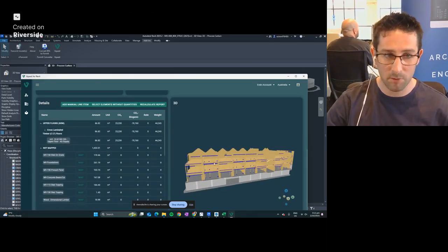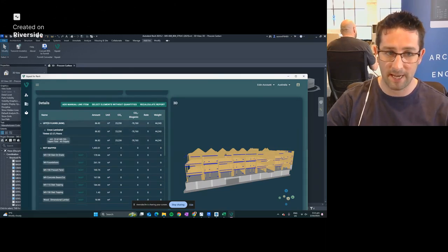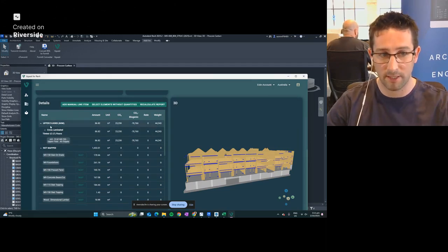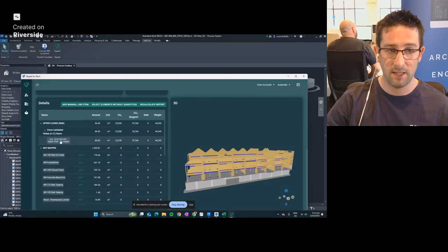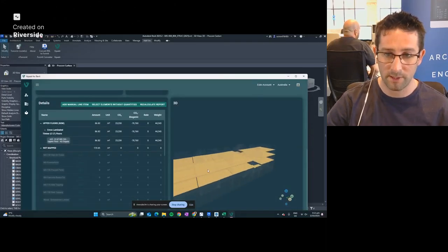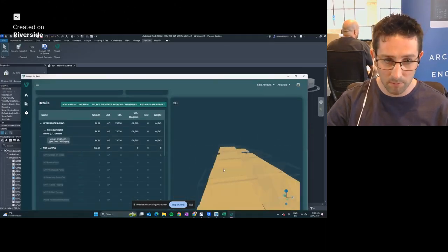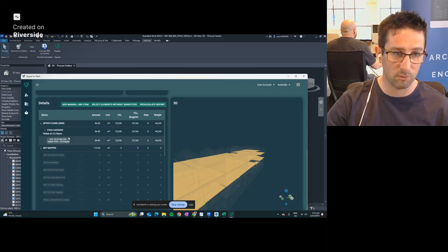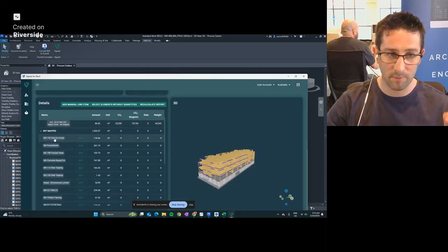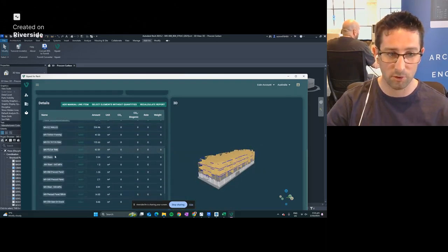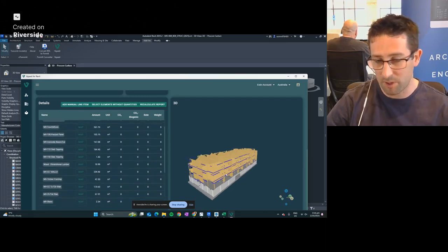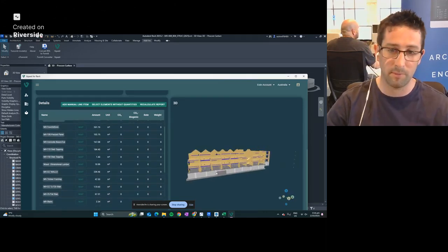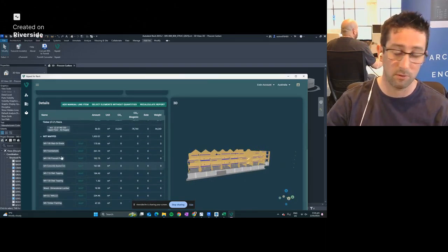That material that I mapped, which was the floor system, has actually been categorized. It's now under an elemental category of upper floors. And when we click here, not only do we see where the material is in the model, we can actually see the total quantity, the total upfront embodied carbon emissions, the stored carbon, the weight, and the cost of that material as well. So it would take about 5-10 minutes to work down through this list with these materials, but you can go as detailed as you want or as simplistic as you want with the level of detail that you're using.